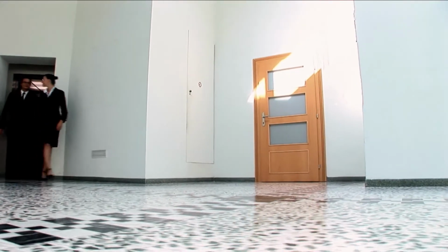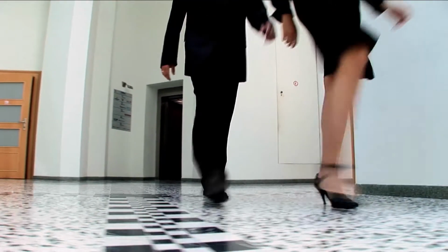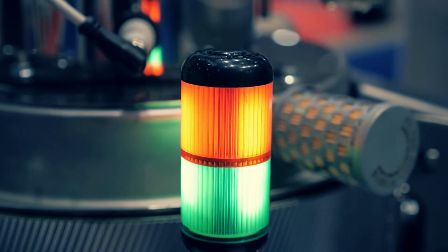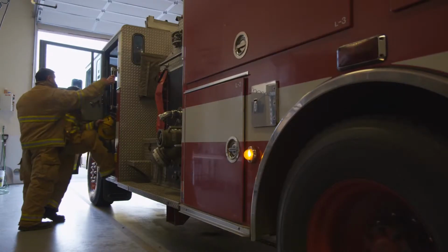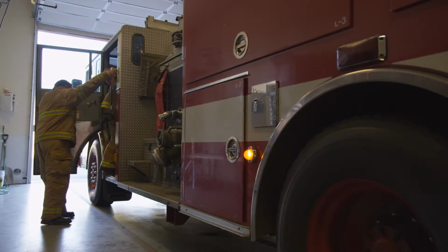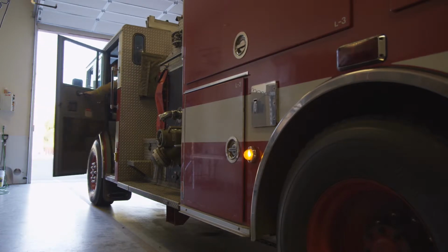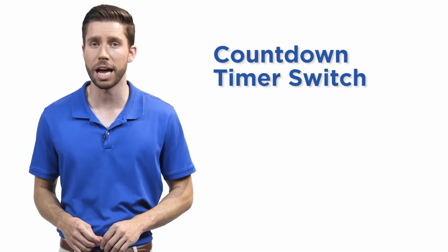Up to 0.1 watts per square foot of lighting in any area within a building may be continuously illuminated if it's designated for means of egress. Lighting in electrical equipment rooms subject to Article 110.26 of the California Electrical Code is also exempt. And lastly, any illumination provided by lighting equipment that is designed as emergency lighting, is connected to an emergency power source or battery supply, and is intended to function in emergency mode only when normal power is absent, is exempt from shutoff control requirements.